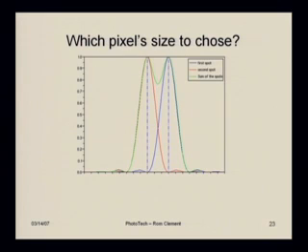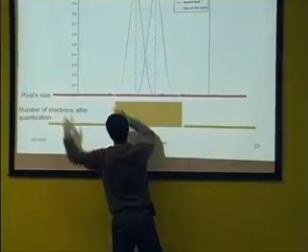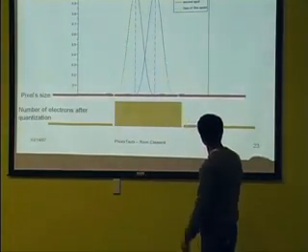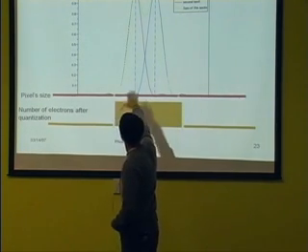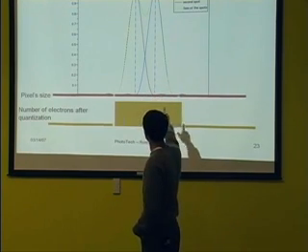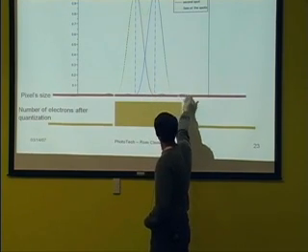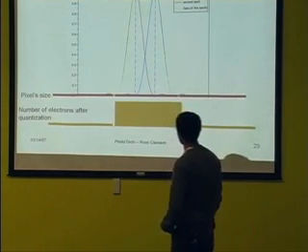But we need now to add a sensor and therefore spatial resolution. So let's start first with the first sensor. So this is 1 pixel, and the second one, and the third one. And what's going to happen here is that my pixel in the middle is basically going to collect all the intensity of light contained in the two peaks, whereas the others will barely get the secondary and tertiary peaks.